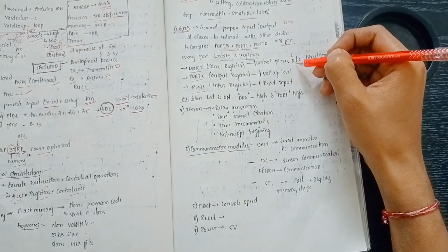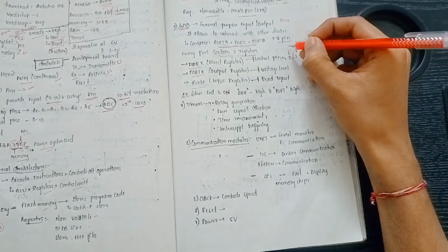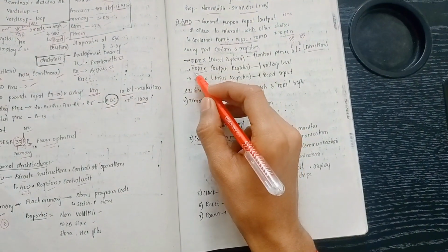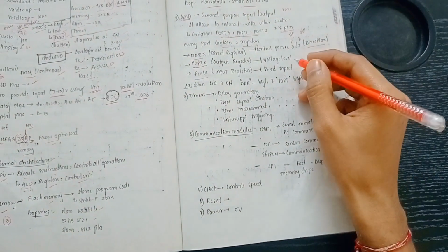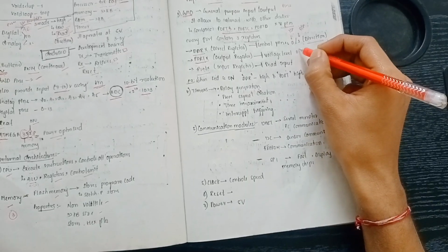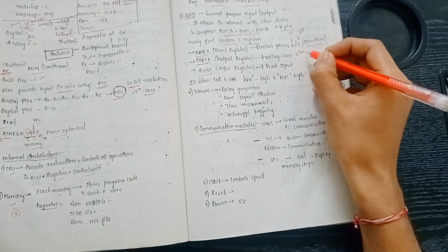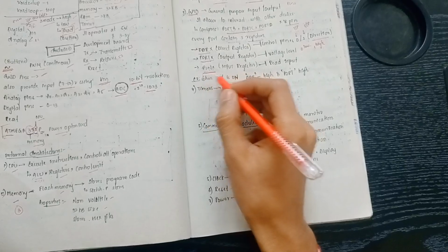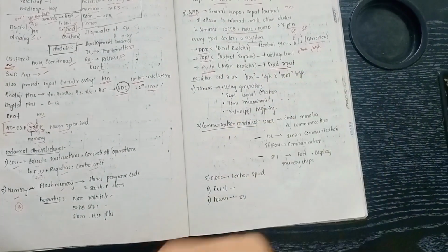When the value of the DDR register is 0, it indicates input, and when the value of DDR is 1, it indicates output. The PORT register is the output register, which indicates the voltage level given to the ATmega. When it's 0, it indicates that the voltage is low, and 1 indicates high. And the PIN register reads the input given.